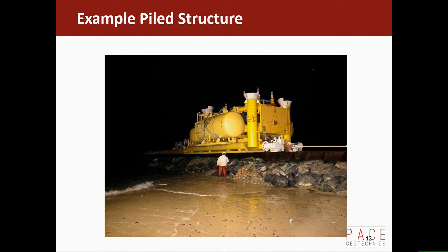And the way they actually do those is to have a structure at one end, a bundle which includes all the pipeline, water injection line, and an umbilical all wrapped up together. And they have a railway line going inshore, and they just pull it off with the vessel, float it out, and then sink it all down onto the seabed. And it works well for anything up to 7 kilometres. It means there's less offshore time required in commissioning. You can see the pile guide, and that white thing at the top is just a guide for the piles to be stabbed into. So they crane the pile down and lower it into that guide and then hammer it home.